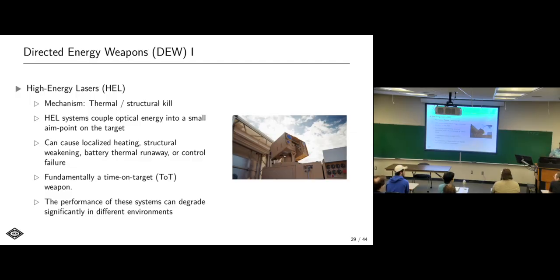So when we're talking radars, a lot of people might think of, if you've ever been on a plane at an airport, all U.S. airports have the standard air surveillance radar. It's that red tower with the parabolic reflector rotating. Yeah, we don't use that anymore. It's good enough for large, slow airliners in a known location. For something as small as a drone, it probably can't even pick it up.